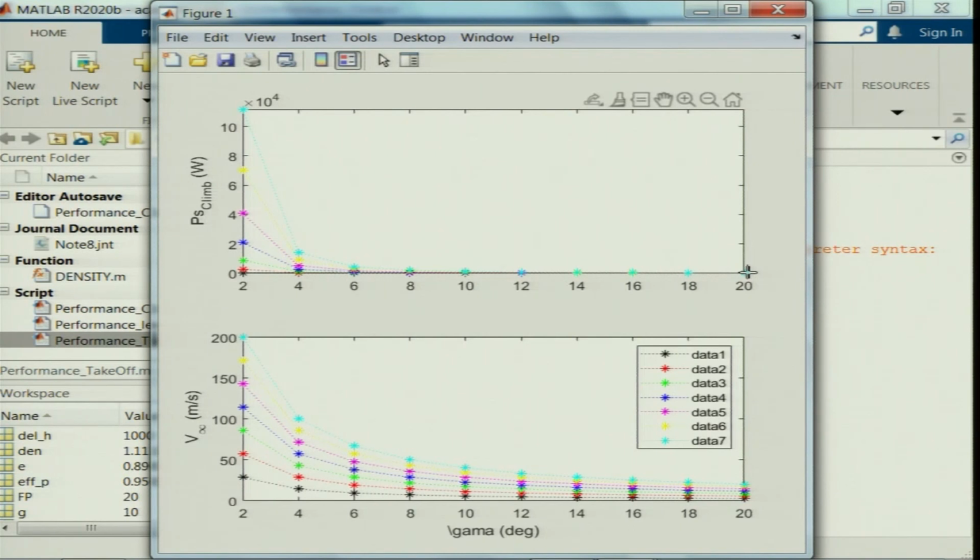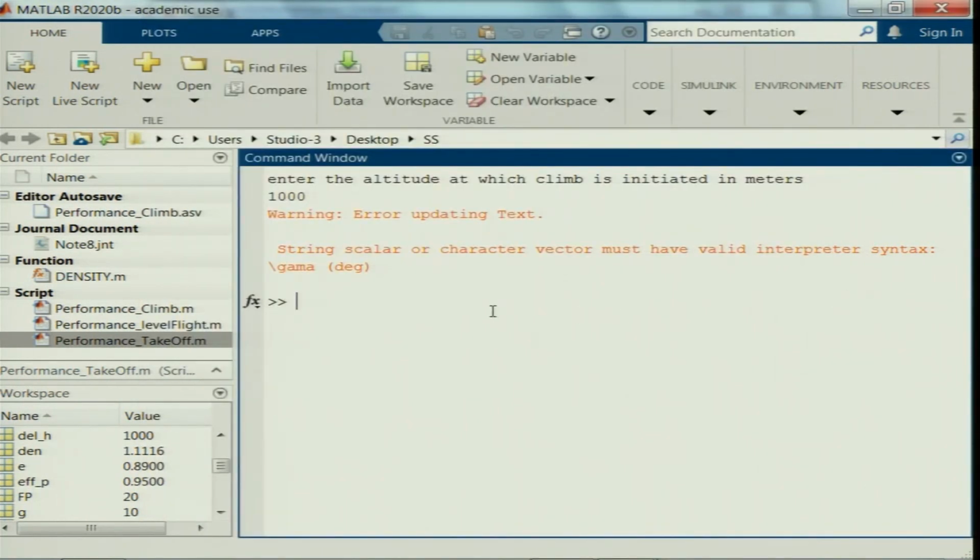the power required. So, maybe the scale is quite big, right, here it is 10 power 4 approximately. So, you require about 392 watts, right. That means, if you take a 6 cell battery, each LiPo battery is approximately 3.7 volts, times 6 is like 22 volts, right.